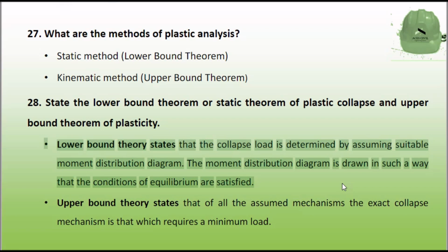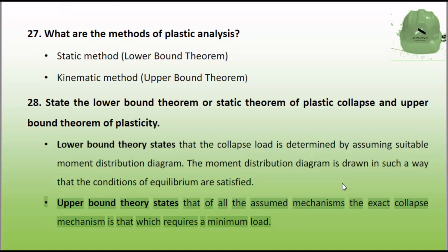Lower bound theorem states that the collapse load is determined by assuming a suitable moment distribution diagram. The moment distribution diagram is drawn in such a way that the conditions of equilibrium are satisfied. Upper bound theorem states that of all the assumed mechanisms, the exact collapse mechanism is that which requires a minimum load.